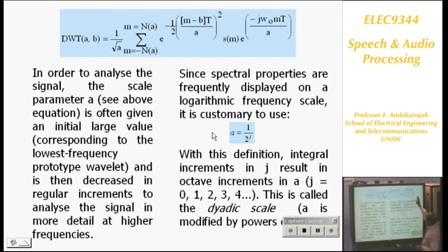And you just continue applying this, and that's what I'm explaining, how to convert between scale and frequency. You can make sure that the frequency positions are such that you select only 8 wavelets. The second one is like an octave of the first one. So if the first frequency is 100 Hertz, the second one is 200 Hertz, the third one is 400 Hertz.